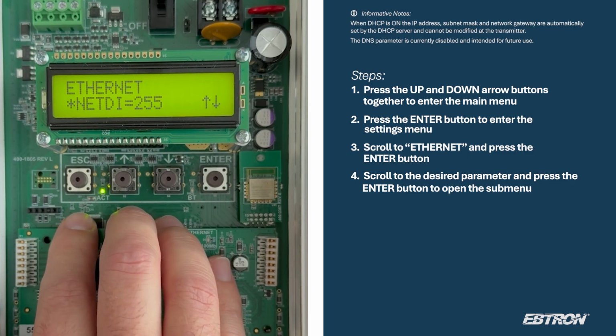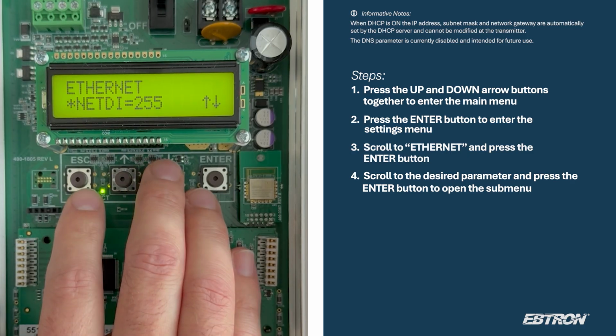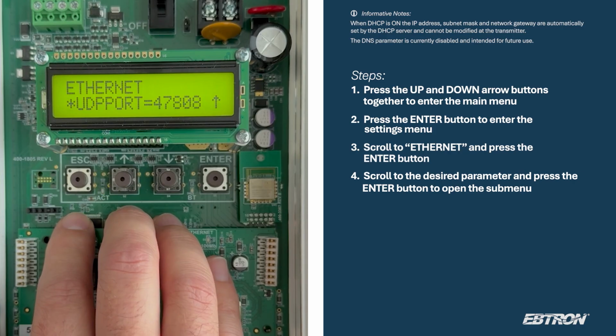Device Instance Number. This assigns the transmitter's BACnet device instance, allowing it to be uniquely identified on the BACnet network. By default, this is based on the last octet of the transmitter's MAC address, but it can be changed if needed. BACnet UDP port. This sets the UDP port number used by BACnet IP communications. The default port is 47808, the standard for most BACnet IP devices. This setting typically does not need to be changed unless your network integrator specifies otherwise.